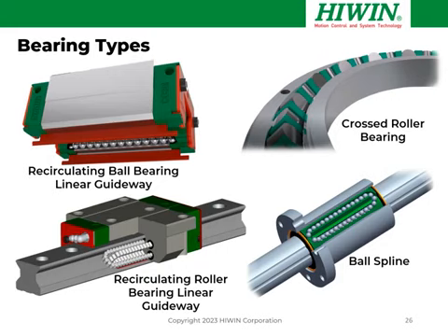Crossed roller bearings consist of alternately crossed, precisely machined cylinders that ride in a precision ground pair of V-grooves. They can be either linear or rotary, both types are commonly found. They provide very smooth motion because of the rolling, non-recirculating bearings. They also can be very accurate because the machining tolerances on the V-grooves can be controlled to extremely tight tolerances.